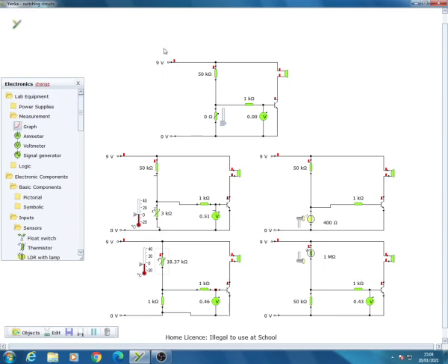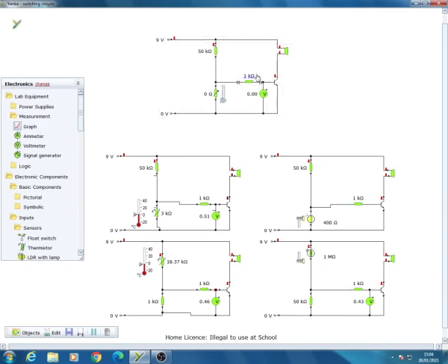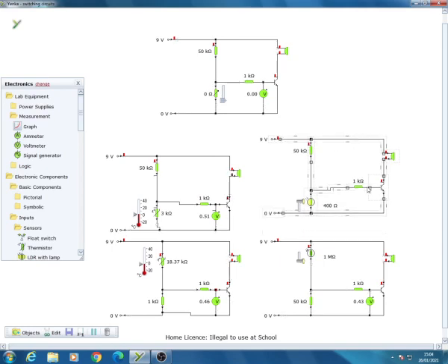Okay, so it's quite a long explanation, but basically this is your basic circuit. I can then change the variable resistor and put a light dependent resistor on and get it to switch on when it is dark. So light dependent resistor on the bottom, it will switch on when it's dark.